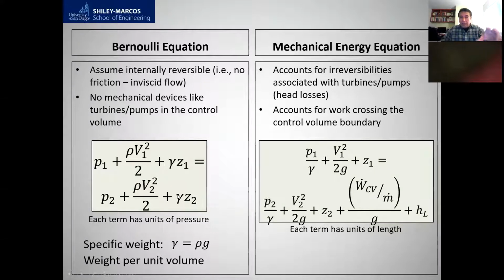But the Bernoulli equation will be simplified to a very compact form called delta P equals 1/2 rho V squared, which is the difference between the stagnation pressure and the static pressure. We measure that by using U-tube manometers, or we use a pitot tube that we insert in an air duct, and then we can measure the differential pressure also. Okay. So that is 1/2 rho V squared.